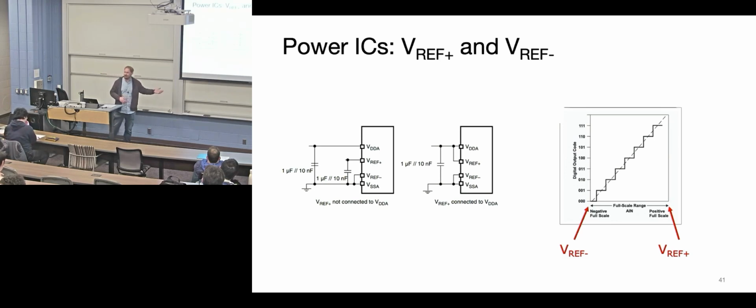But in the real world, you have a chip that has certain capabilities. Lower end microcontrollers may not give you a negative reference voltage as an option. It may always be ground. Sometimes they won't even give you a positive reference voltage. It'll always be VDD. On your chips, I believe you get control over both. So you could have an external reference source come in and be the negative rail of your ADC, and you could use the internal or another reference source as the top.